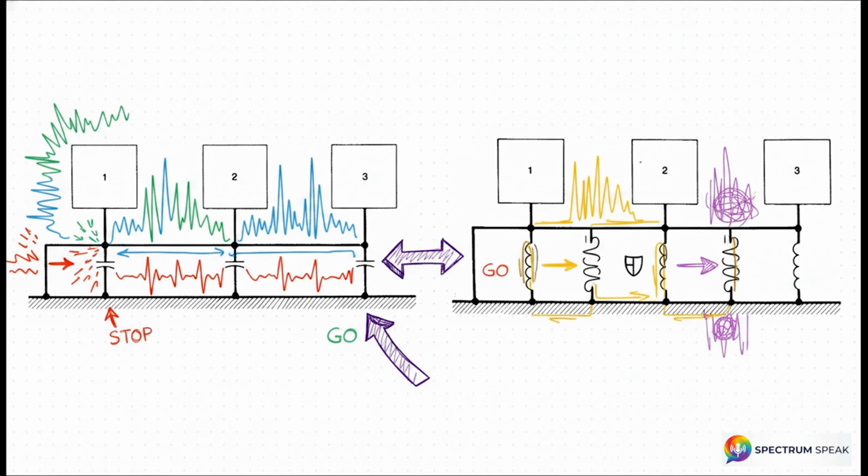On the left, we've got a capacitive hybrid ground. By sticking capacitors between the circuit and ground, we create a really high impedance at low frequencies, so it's effectively a single-point ground. But at high frequencies, those capacitors become low-impedance short circuits, safely dumping the RF noise to ground. On the right side, we have the exact inverse, an inductive hybrid ground. Here, inductors pass your low-frequency 50 or 60 Hz safety currents without breaking a sweat, but they firmly block high-frequency noise from radiating out over your power cables.